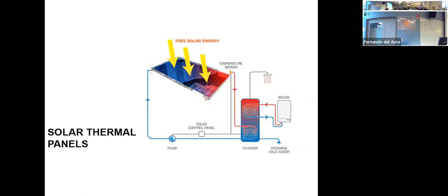So when the water is warm, it's prone to generate this bacteria. So we need to raise the temperature of that water to 140. We kill the bacteria. So that's why we cannot go below 140. That is this circuit, because it's in contact with our skin, and we can even drink it. So we need to heat it up to 140.